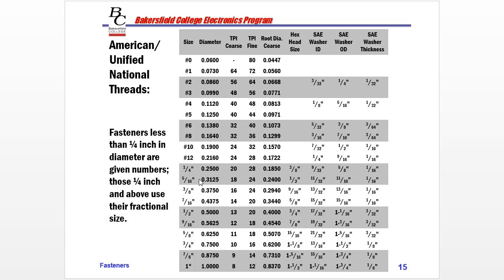Of course, 1/4 inch is 0.25 decimal. And we have the normal 1/4-20. And so generally we'll call it 1/4-20: 1/4 inch, 20 threads per inch. And then the fine thread version of 1/4 inch is 1/4-28. So you can see if we have a 1/4 inch bolt, that is the major diameter, and we actually have a